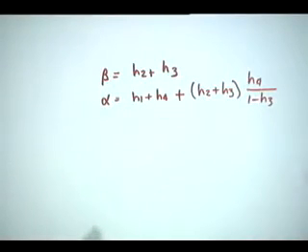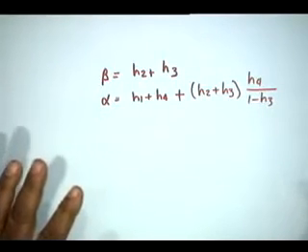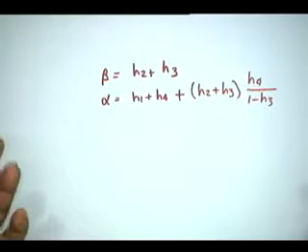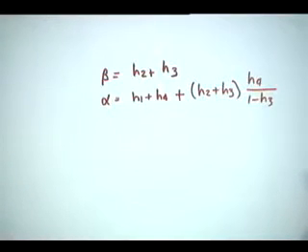Okay? So, either the highest power coefficient plus 1 or minus 1 actually is a welcome step because it reduces your effort. All right. If it is linear phase, that also reduces the effort considerably. If it is not linear phase, neither is the coefficient of the highest power term equal to plus 1 or minus 1, even then, with a little bit of ingenuity, you can apply some of this simplification.